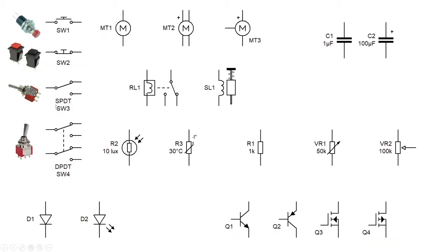In this case, we often see these terms here, SPDT or SPST or DPDT, as is this one. What that means is single pole dual throw, or single pole single throw if it's an SPST. A single throw would not have this one here. Single pole means there's just one connection being made, so it's just one circuit being dealt with.